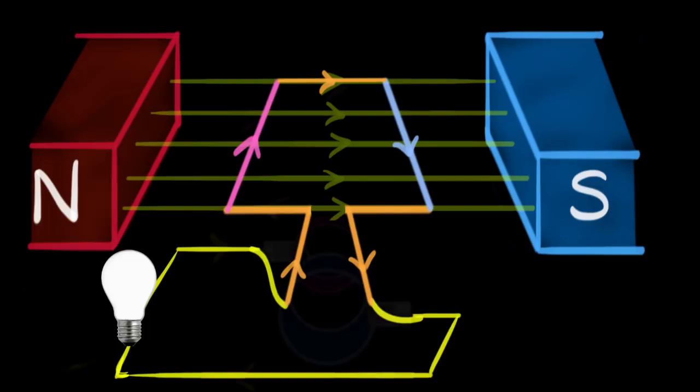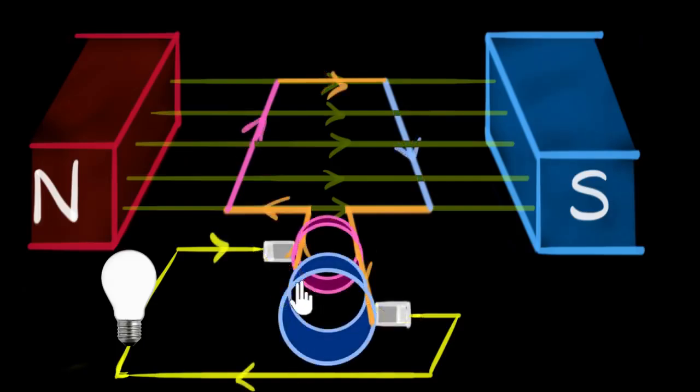It looks somewhat like this. So basically we have two metallic rings, the pink one and a blue one. And what you may not make out from my diagram over here is that each ring is connected to one wire only. So the pink ring is only connected to the left wire, and the blue ring is only connected to the right wire. And these wires are connected to carbon brushes, which is also conducting, and they are just touching these rings so that there is a metallic contact, but they're not stuck to it.